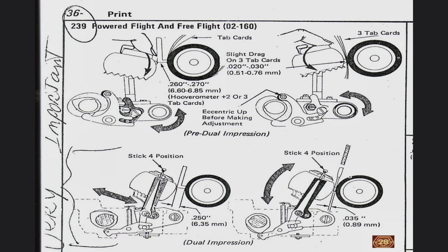Notice that in the case of the pre-dual impression machine, the print cam is really a cluster of two complementary cams. On pre-dual impression machines, not only the rearward drive of the rocker toward the platen is accomplished positively, but also the return of the rocker into its rest position is accomplished positively.